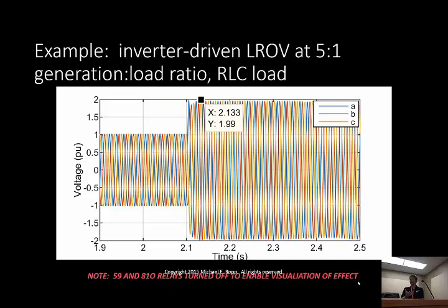I mentioned one of them to you before, and that is that with an RLC load like this, a purely impedance load, in order to drive the voltage up, I've got to source the power, right? I've got to have enough energy to hold that voltage up there. Well, the PV is energy limited. There's only so much behind the inverter. It can't do more than that. In this simulation, that is the main thing that happened. It got up as high as it could, and then there's just no more power, right? So it can't drive it all the way up to the square root of 5. But you notice it was higher than was seen in the experiments.